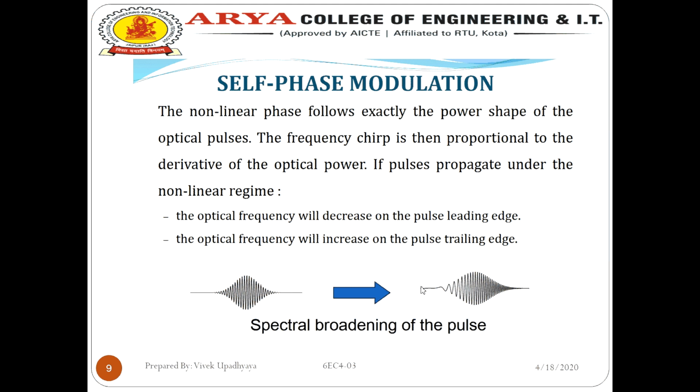Although the SPM can simply be used for wavelength and frequency shifting, it has found a major application for pulse compression within single mode fiber transmission. In this context, SPM effectively imposes a chirp or a positive frequency sweep on the pulse.